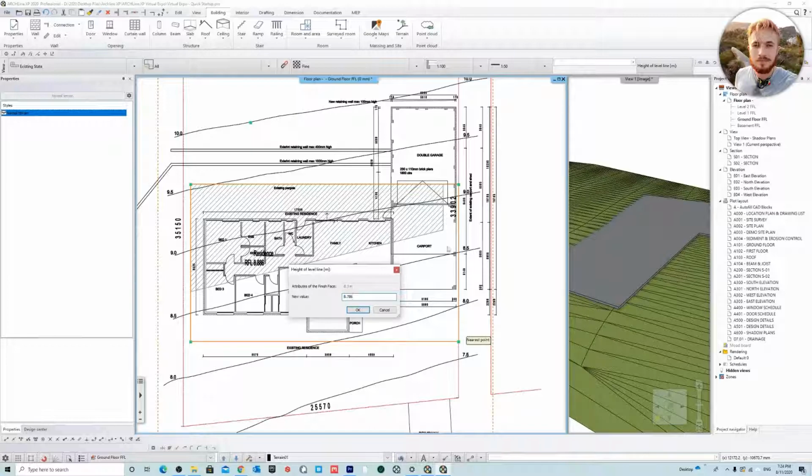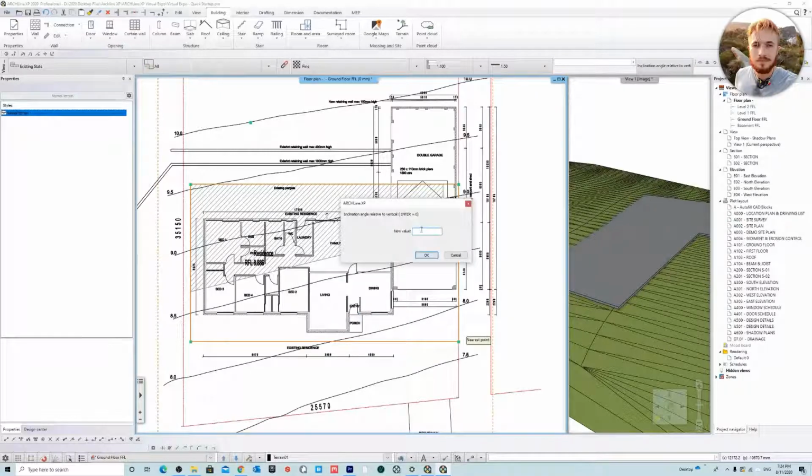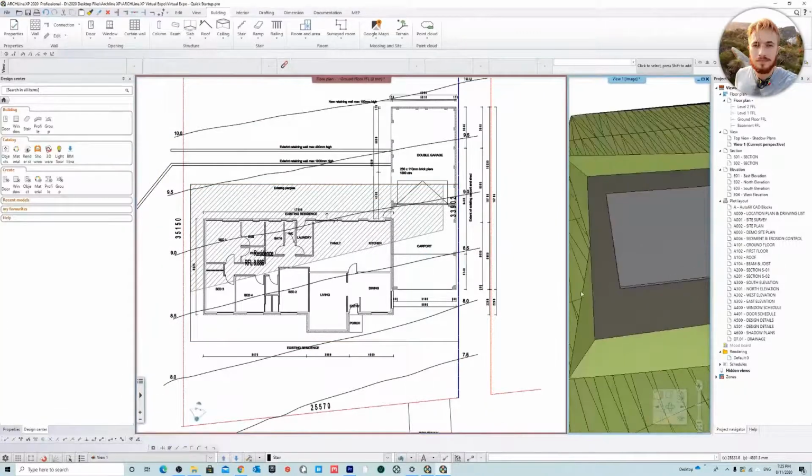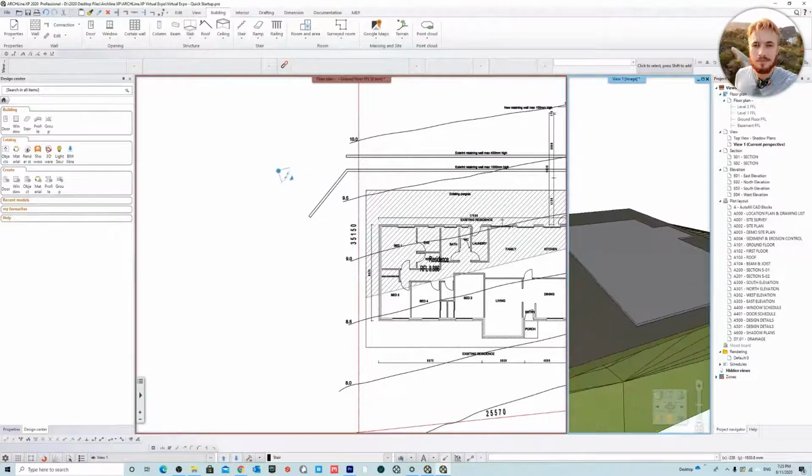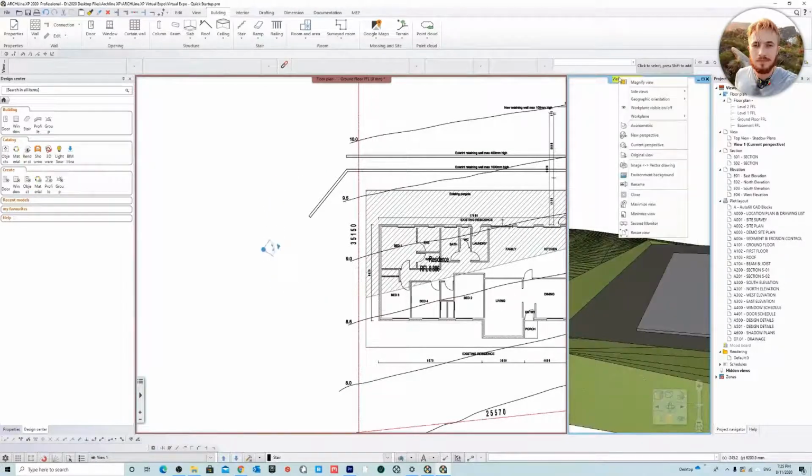So that means that this flat part is going to sit beneath the slab. Okay, so if I just go okay, and I'm going to select an inclination angle, and that's just the terrain surrounding it. So what we've got to do now is maybe just put in 60 degrees and see how that looks. Okay, so you can see now we have a building footprint, a building pad.